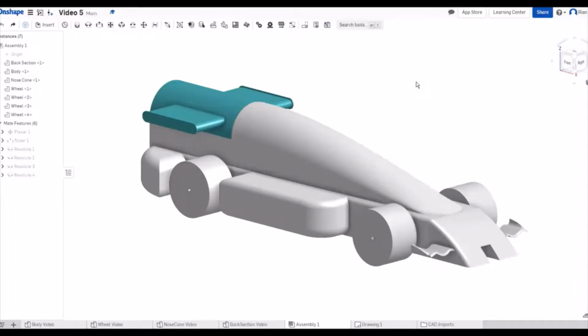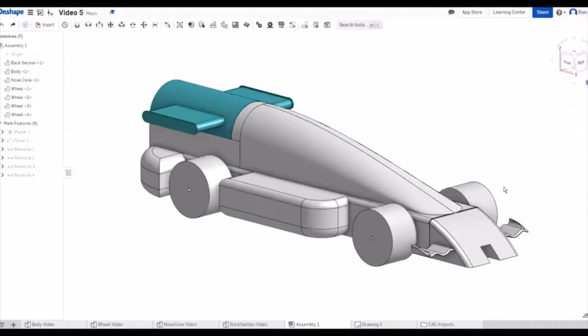So these fillets are really easy, but the important thing about making fillets is actually determining how big you want them, because you don't want them so big that there's no actual pod left and you're cutting into no-gos, which is an important but annoying feature of F1 schools, which you can't actually cut into. So you don't want them too small so that they don't actually have any effect at all. So you can see, if I switch back to a normal view, that the rear pods have slightly larger fillets.